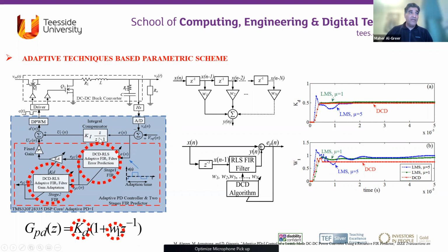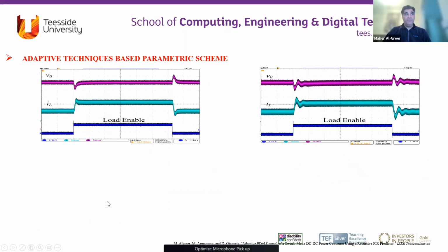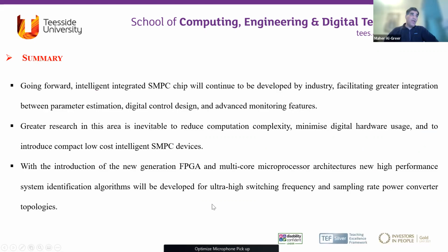And we also use the integral controller, without any excitation signal, to amplify the error signal as an excitation for this control system. You can see in this response the accuracy of estimation of these parameters, the KD and KP, or the W1, which is the filter parameters, and the gain of this system. And this compares the method that we developed with the conventional PID control. You can see here that they produce an efficient response during the abrupt load changes, but here there is some oscillation and they cannot track any changes in the system.